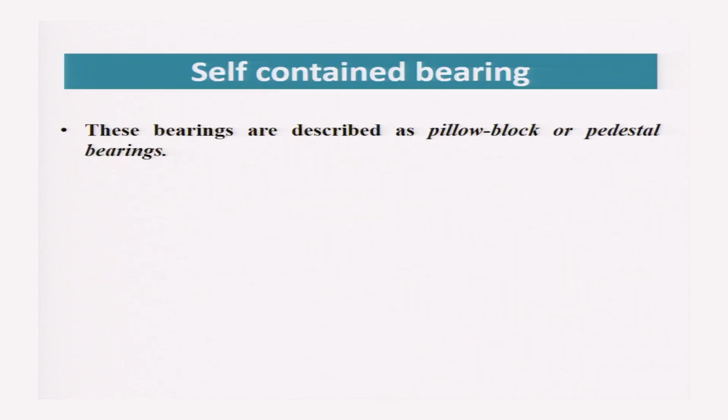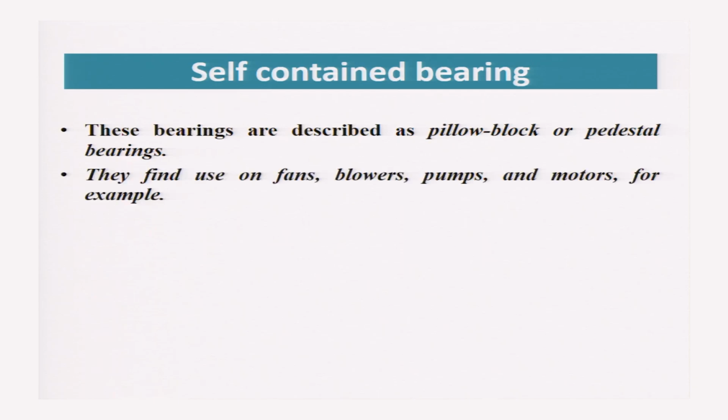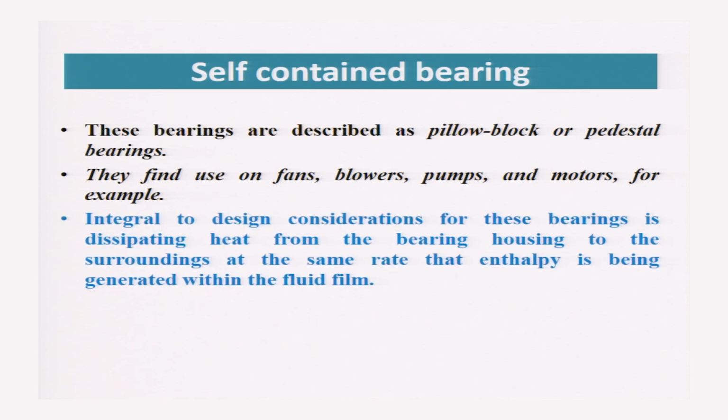These bearings are described as pillow block or pedestal bearings. They find use in fans, blowers, pumps and motors. Integral to the design consideration for these bearings is dissipating heat from the bearing housing to the surroundings at the same rate that enthalpy is being generated within the fluid film.